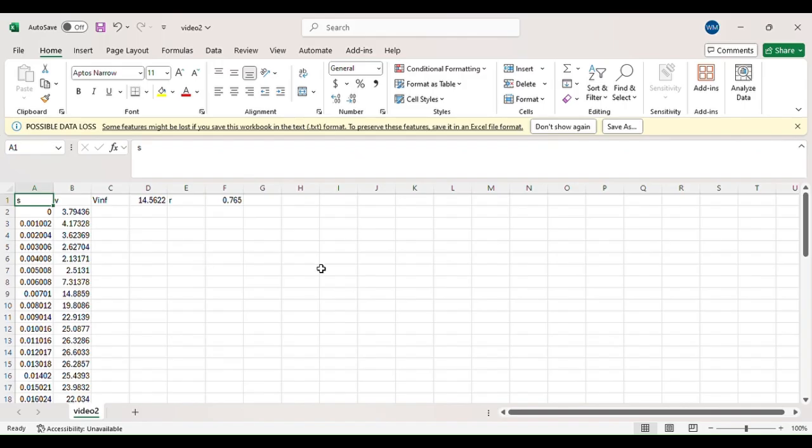Now that data acquisition using ANSYS Fluent is complete, it is time to generate the plots for coefficient of pressure and velocity over the entire surface of the cylinder. Here in this column I have the arc length, which was measured by Fluent, which denotes the point on the cylinder at which velocity was measured.